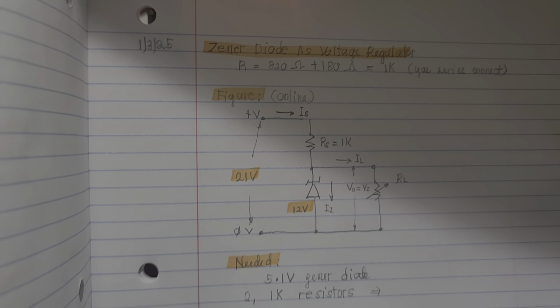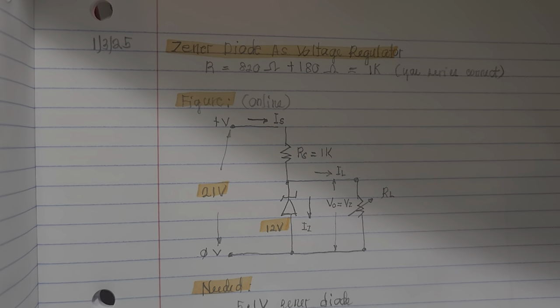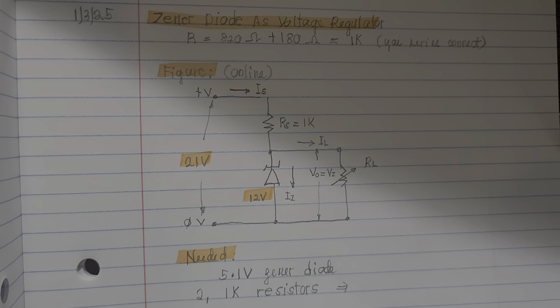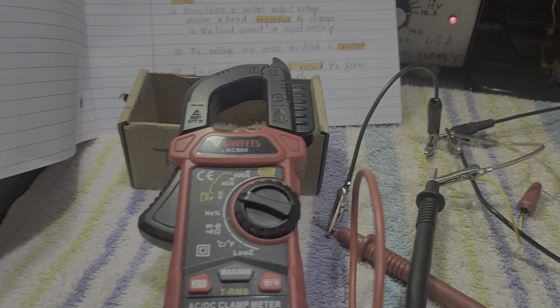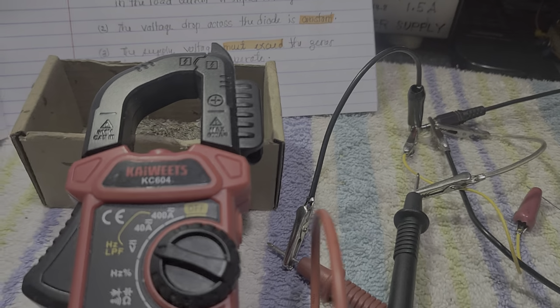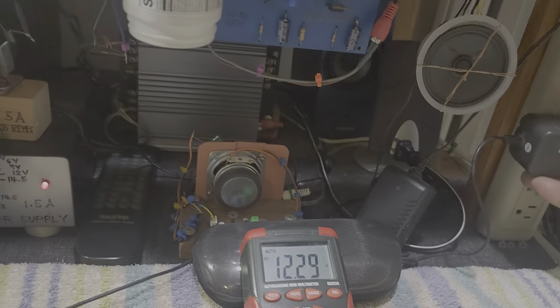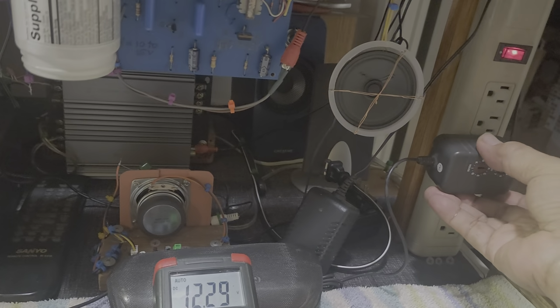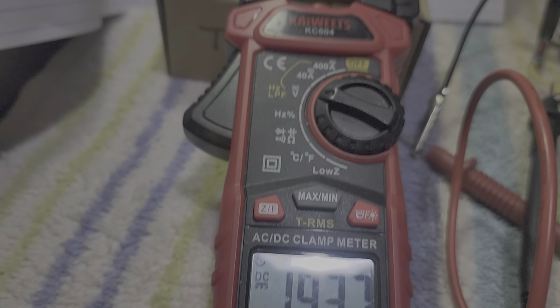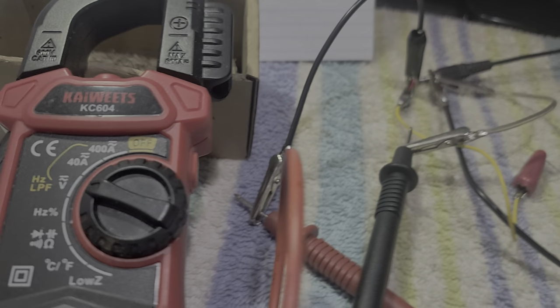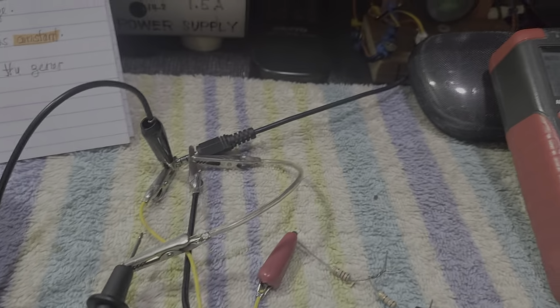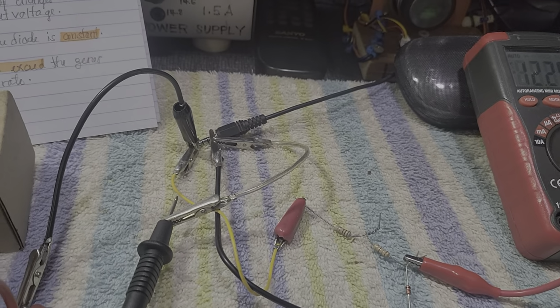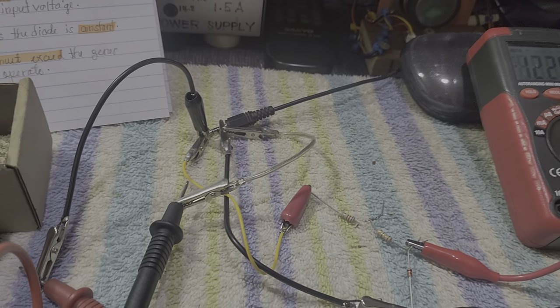That's how we analyze the concept of how to assemble a Zener diode. And like I have shown you the actual circuit now. Like what I said, the voltage input to the Zener diode is this adapter here. The output of this one is, no, 19 volts, 19.39. And the voltage output across the Zener diode is 12.29. So actually, a Zener diode could act as a voltage regulator.